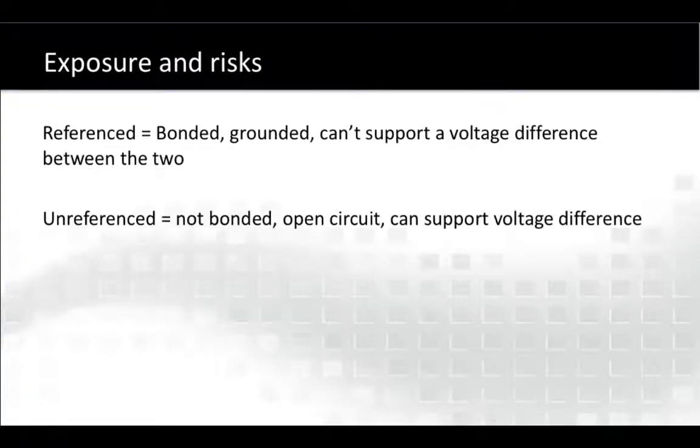When I use the term referenced, what I mean is that the structures are bonded or a structure is grounded, and therefore it can't support a voltage difference between, say, pipeline and ground, or one pipe and another pipe, or between there and a fence. When something is unreferenced, what I mean is that it's not bonded, there is an open circuit, and if that's true, then if voltage is present, then it can support that voltage difference.